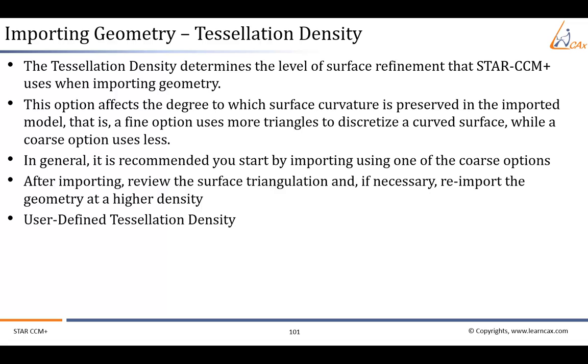Selecting the user-defined tessellation density option automatically activates the Show Detailed Tessellation Parameters option. The detailed tessellation parameters are then displayed within the Import Surface Options dialog. You can edit these parameters as required.